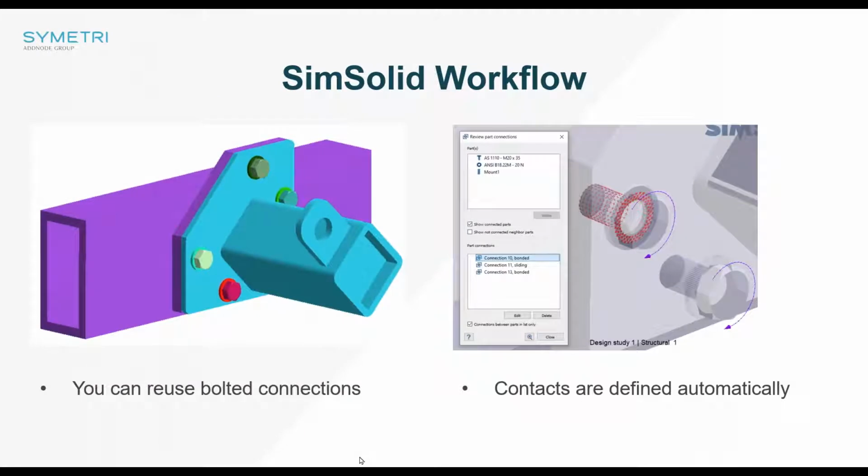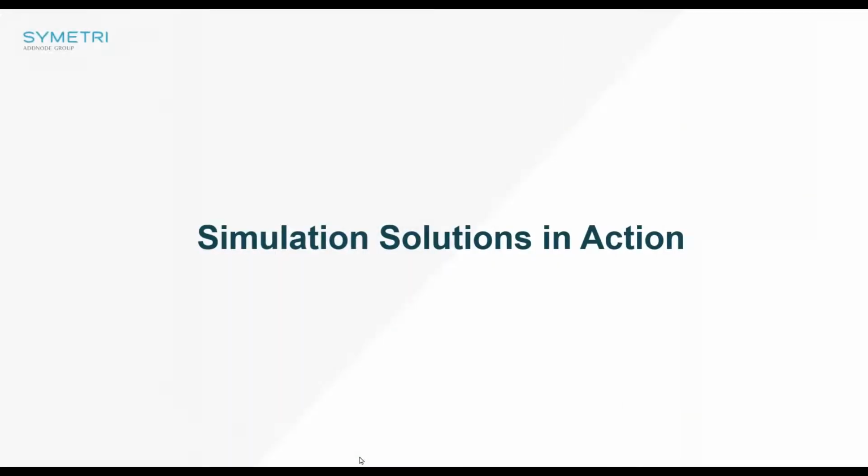And in SimSolid, unless you've already been having a go on the software, I would suspect you can reuse the bolted connections. And the part I like most about it is that it creates contacts automatically, and they are the right contacts. For example, it creates bonded and sliding contacts. So that is a big plus within SimSolid. So I'll go through these different workflows. Okay.